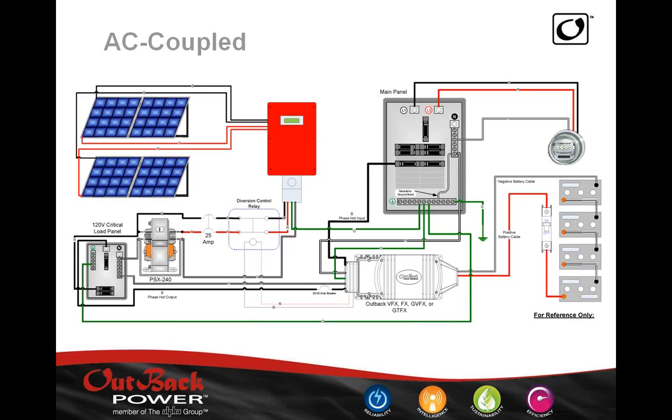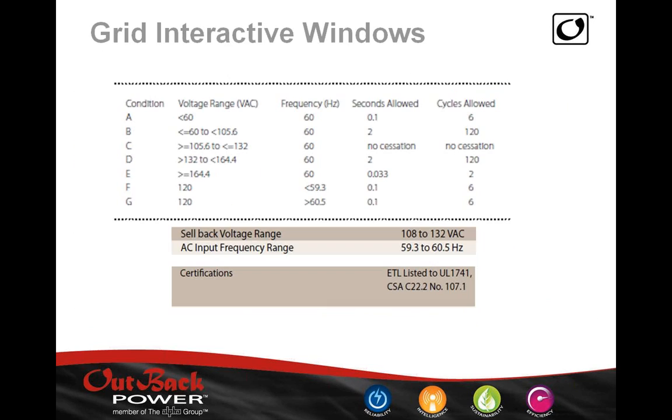Initially, a lot of the solar systems that were being installed were just grid-tie systems, battery-less systems with no backup, where you only had your PV array and your grid-tie inverter, and then that went onto the grid. But the problem, again, remember our table here, is that the inverters for UL 1741 are fixated on looking for these voltages and these frequencies.